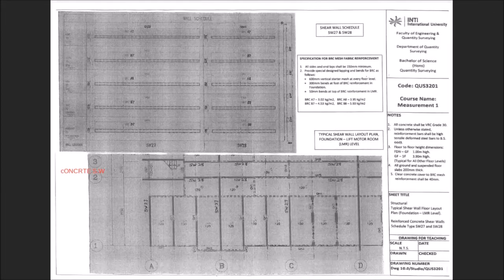Okay, what is the category? If I would like to measure the first one, I give you one example. If I would like to measure the first one in this category, 175. So 175 falls under which category? 175. Exceeding 150, not exceeding 300 mm. Okay, so this is the first category. You have to measure in meter cube. So how do you want to measure?